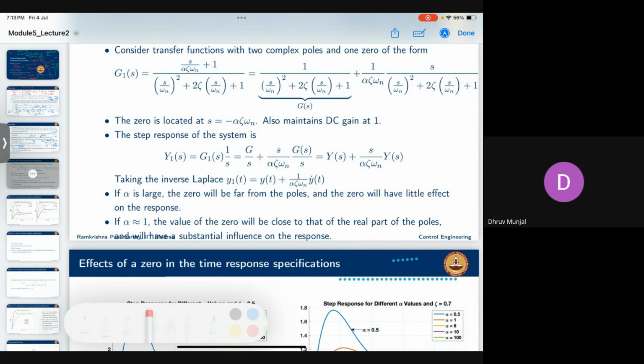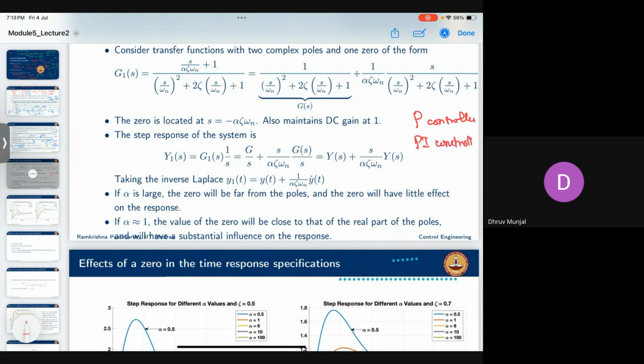There are popular systems with only a P controller, or you can do with a PI controller. For some systems the overshoot won't happen, or after introducing some integral gain, it would come to a stable region. So PI is enough. Sometimes you would go with a PID controller or a PD controller. UAV based systems are okay with a PD controller. There are many papers with PD controllers for unmanned aerial vehicles, the drones and all. So you don't really need every controller for every system. You should be able to pick what you want.